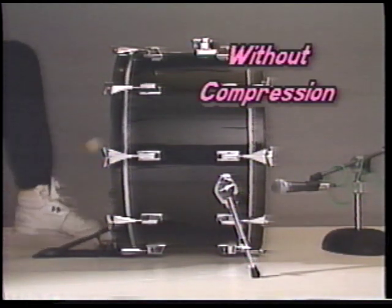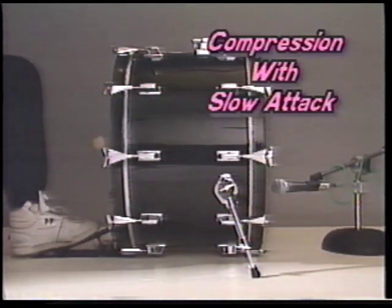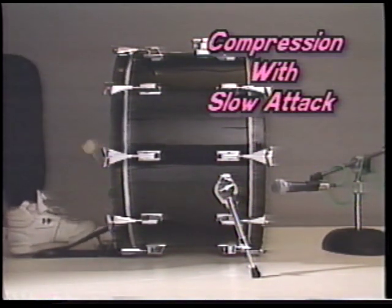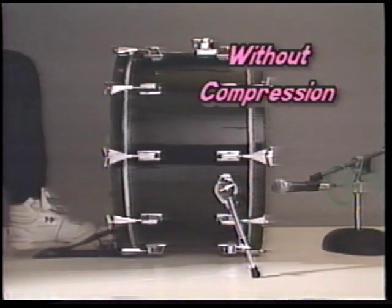Another useful example would be if you had a kick drum with no punch. By setting a slow attack and a reasonably low threshold, when the beater hits the head, the transient of the hit will pass before the gain comes down. This reduces the floppy overtones of the drum. The result gives the kick drum a tightness with substantially more attack and percussiveness. I often use this technique on drum machine-generated kick drum and snare sounds, which in general are dynamically restricted.